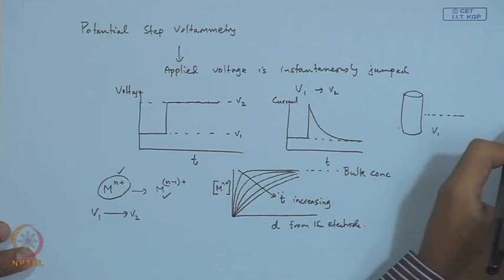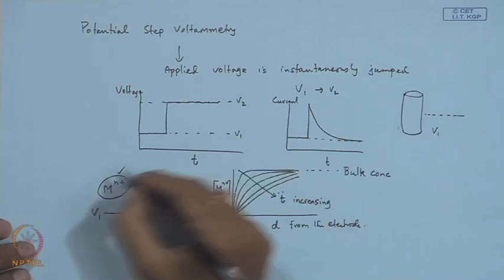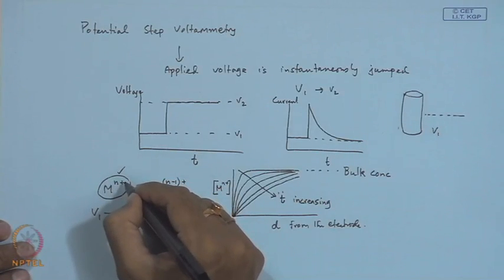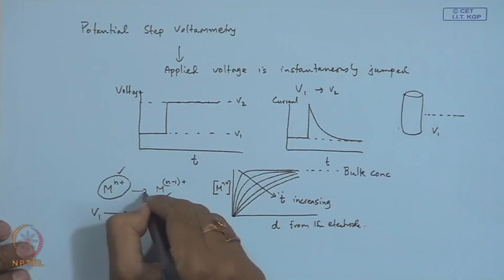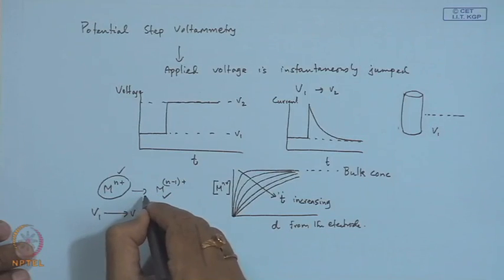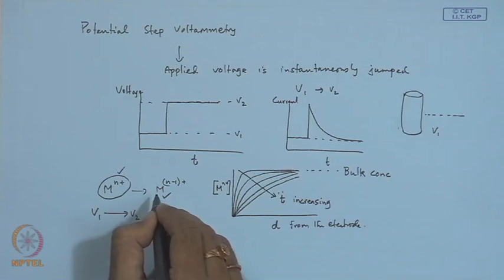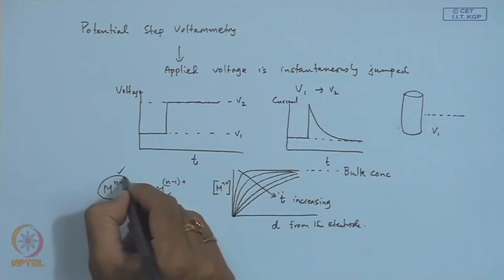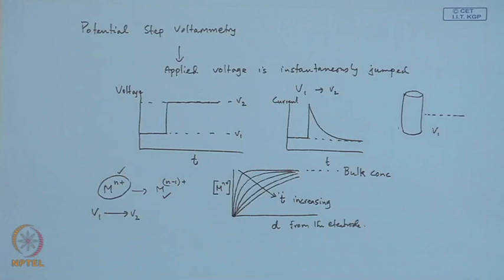Okay. So, the supply of fresh unconverted metal to the surface depends upon the diffusional flux, and at short time the diffusional flux of this metal is high, as the change in concentration between the bulk value and that at the surface occurs over a short distance.